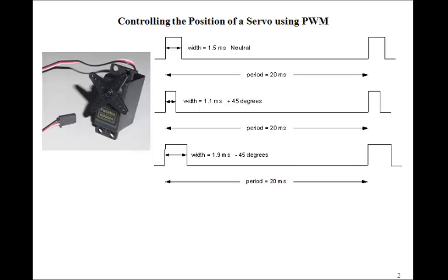Well, this means that the 8-bit PWM signal that we saw in the last lesson that we used to control the speed of a DC motor won't really be adequate to do the servo because the resolution won't be high enough to give us very much resolution way down here for low duty cycles. So we really need a counter, say a 16-bit counter, that can have a higher resolution.